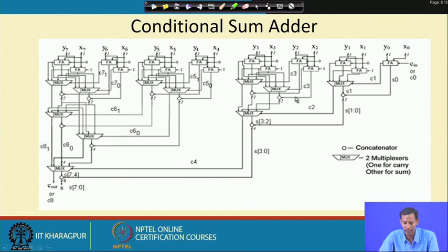So now I can generate the carry output bit and another output, this 2 bit. Basically, what am I getting? I am getting 2 bits here. Why 2 bits? One sum from this, another sum from this. As these sums are concatenated with the previous sums, I will get 2 sums here and concatenate with the previous 2, and from here I can compute the last 4 bits of sum and the corresponding carry out bit.